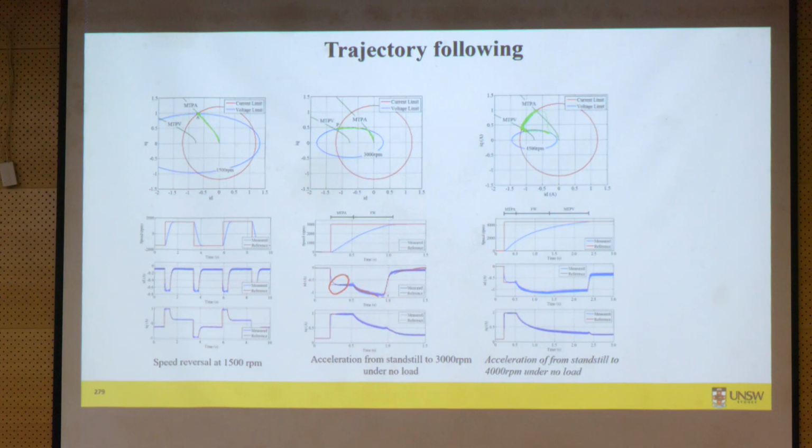If we had kept the torque high, then the ID current would have settled here, okay? But in this case, I think we have applied low torque, so the ID current has come back here. And you can see also IQ current, how the IQ current was highest under MTPA, but under flux weakening and MTPP, it was dropping, okay?